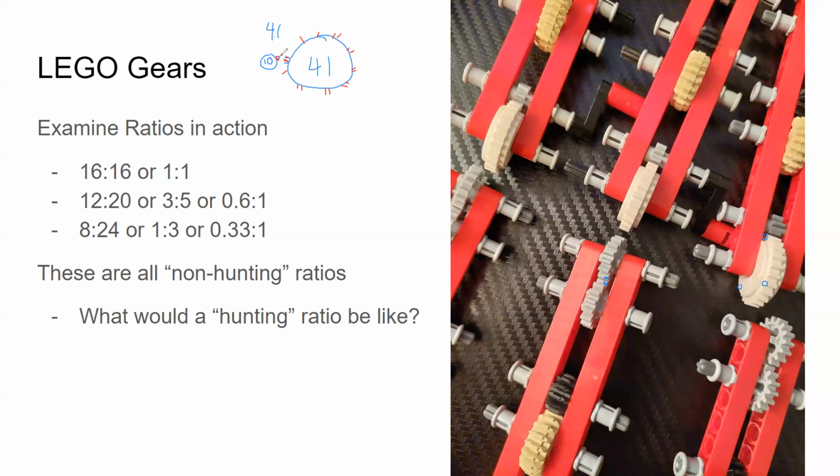It's kind of like if you're not feeling great and you hang out with a bunch of friends that can help you out emotionally and everything, it kind of restores your health a little bit, right? So you can kind of think of that with this hunting type gear ratio. One bad tooth, when it meshes with all these other good teeth, it kind of hammers it back into shape and keeps it healthy so it can keep running for a long time.